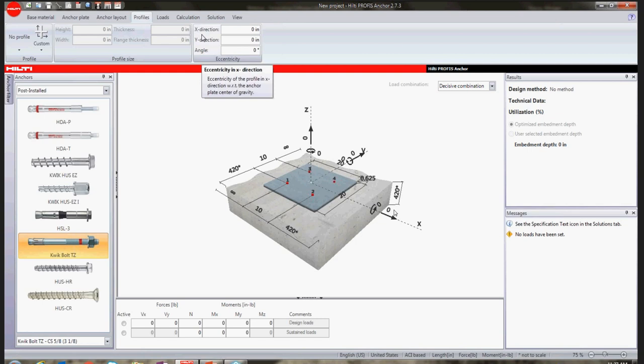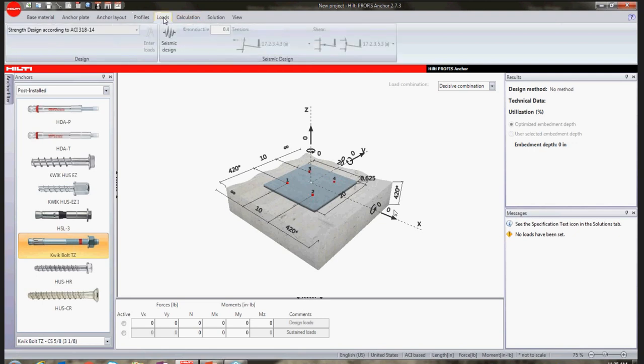If you want to change condition A to shear or condition A in tension, as well as the bar size, you can. What's going to happen when you activate that? The software is going to pull in the appropriate psi factors and phi factors in ACI and use those in the calculation. On the very far right of the screen, moving my mouse again, you're going to see anchor reinforcement.